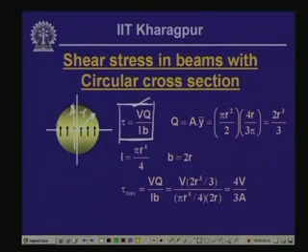Wherever we take any point, the shear stress distribution is uniform over the width. Now, when we are talking about the circular cross section, then as you know, on the surface of this particular beam there will not be any stress. So, in the radial direction there will not be any stress and that will be 0. So, the stresses which we will have are all in the tangential direction, and hence these stresses are no longer going to be parallel to the y axis.